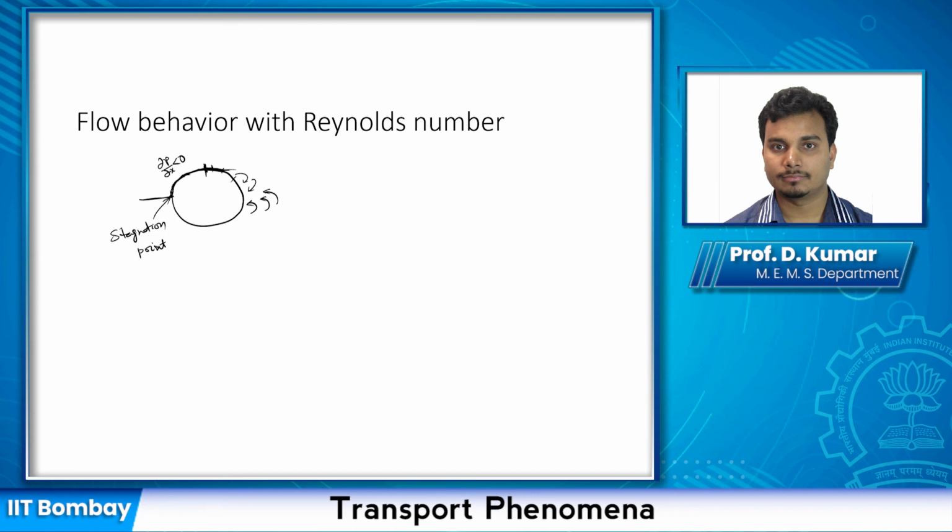There are no eddies or those kinds of things here. The boundary layer remains laminar, but you have wake formation here. Because of the wake formation, you will have some turbulent eddies, but the flow associated with this surface is still laminar. At those conditions, the wake region can be seen as sort of symmetrical.